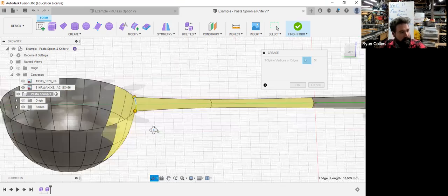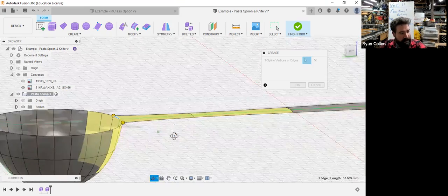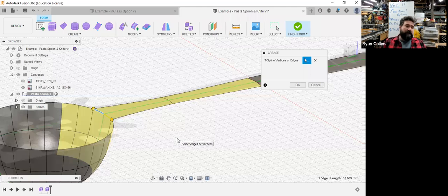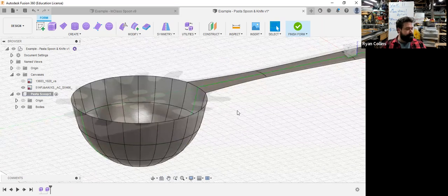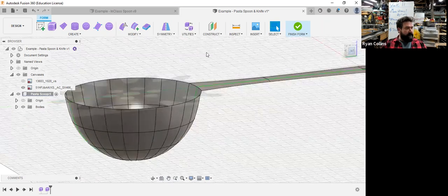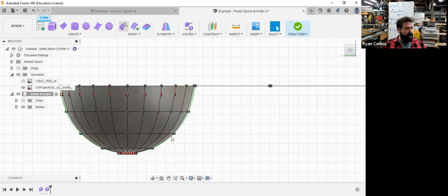So now that bowl has a very sharp edge, it just maintains it. So if you wanted to keep it, crease edge. If not, you can either have left it that way, or you can actually use the uncrease edge tool. Does the exact opposite. I'll say, okay. All right. Go to the side again, and I just want to go ahead and shrink those up again.